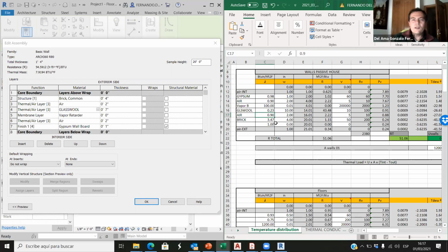And then you make sure that your materials match. Or the other way around, you have a list of materials the construction company has provided you with, so what is the thermal conductivity of the materials that we are going to use? And then you place those materials either in this website or in this Excel file or in Revit.